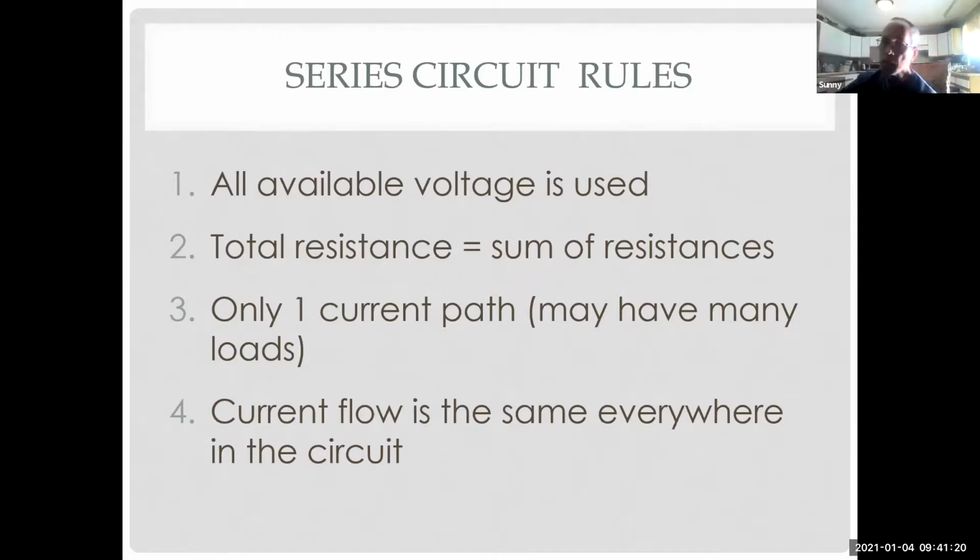Or the resistance will not affect it. What's that? Different resistances will not affect the current flow. Oh, different amounts of resistance will affect the current flow, absolutely. But the current is the same everywhere in the circuit. So it doesn't matter where the resistance is in the circuit, the current flow is the same everywhere. The resistance between two loads is the same at either side of the load. The whole circuit has the same current flow.